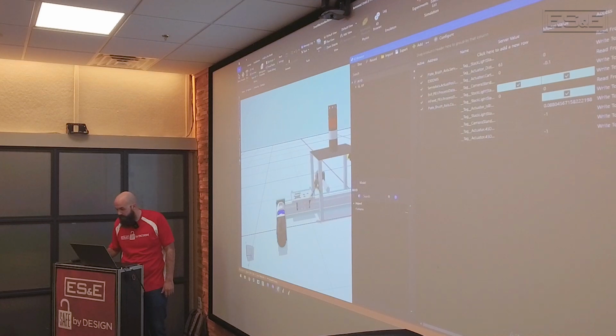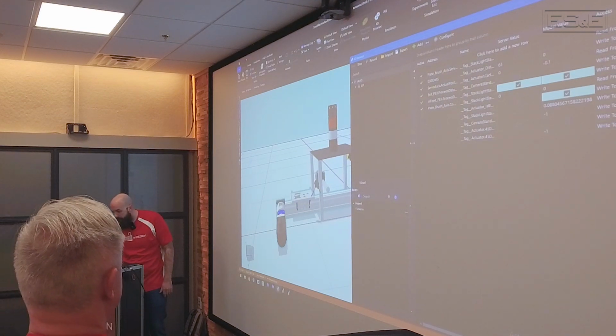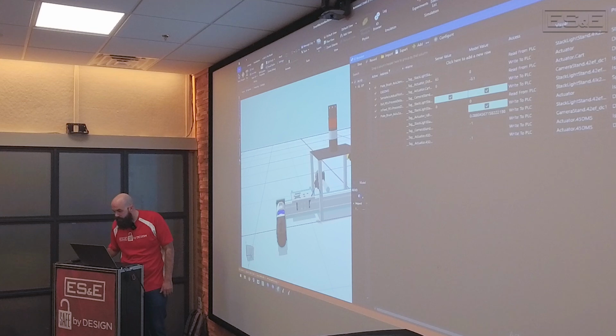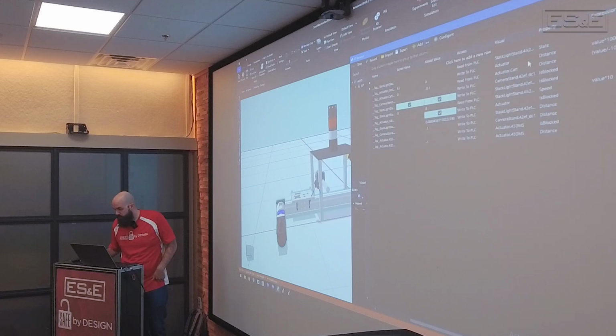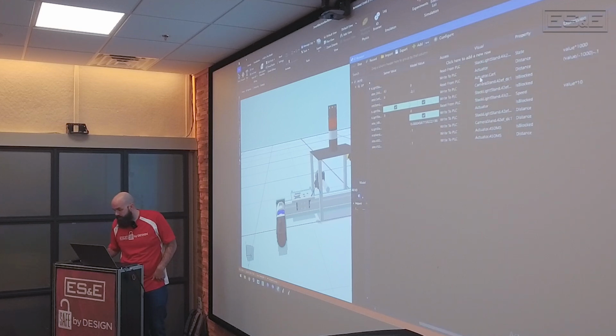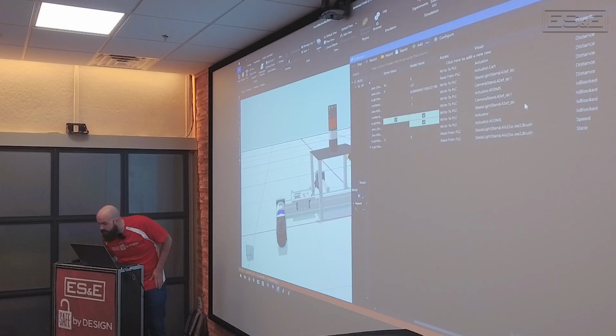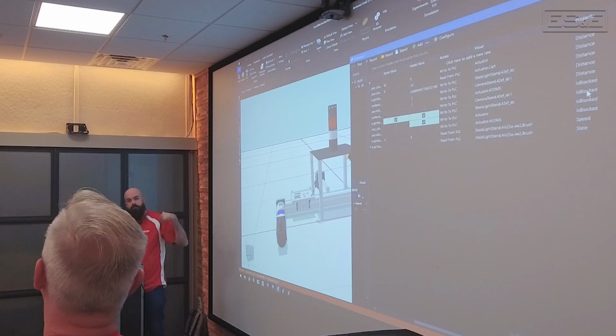So for this photo eye, the in-feed photo eye, let me make this bigger so you can see it. You'll see in-feed PE process data .triggered, right? That's being written to the PLC, and it's just referencing this visual property, which is my 42EF distance sensor, right? And basically, I have a tag in here that's saying if it's blocked, write a 1 to that tag in